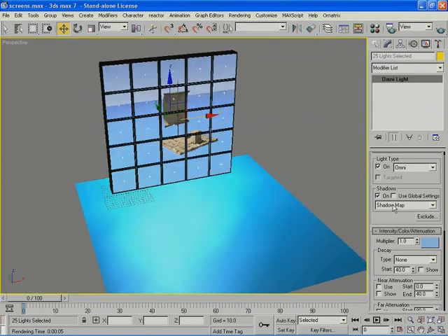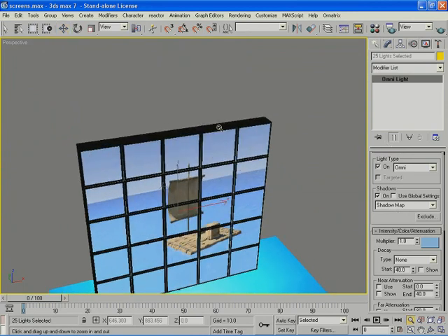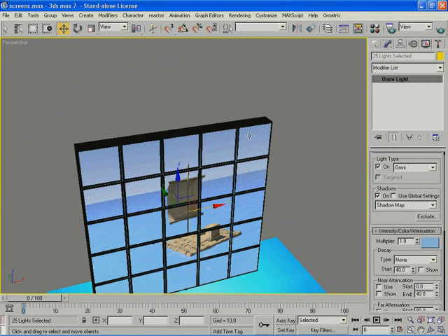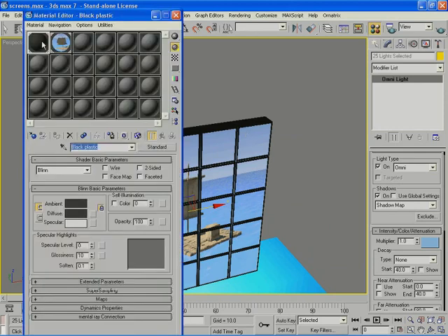What I want is for the plastic to hit the light and make it stop. But since the light is within the TV screen, it's going to cross it and hit the other side of the TV screen next to it, which is not what I want. I want the light to hit its own TV screen side. Therefore, I need to go to my plastic material and make it two-sided. Therefore, it's going to stay contained within the TV screen, but I will not set the screen to be two-sided because I want the light to emanate from that side. So the only way the light is going to go out is from the TV screen side, and the rest will be contained. So I will set the plastic to two-sided and leave the screen set to normal.